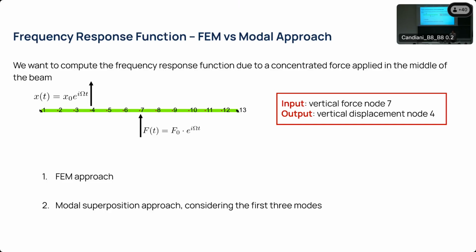If you remember, we have a language that we can use to express the movement of that bridge using the first 3 to 4 mode shapes, the sum of its 3 to 4 mode shapes, to express with satisfactory precision its displacement in the frequency range you're interested in. Then you pass from a system of 300,000 ordinary differential equations to a system of 3 ordinary differential equations. The difference in the computational power you ask and the interpretation of the analysis you need is huge, because you can scale your problem by orders of magnitude.